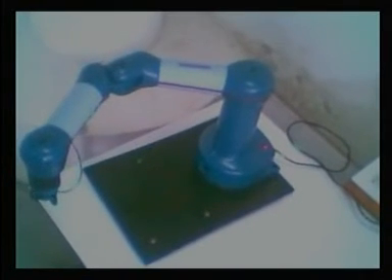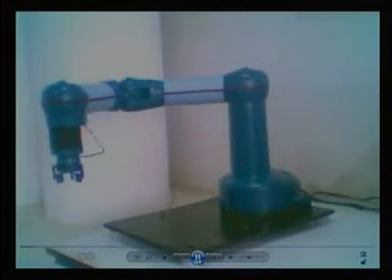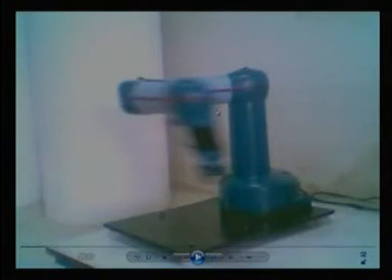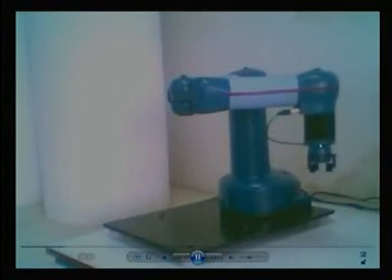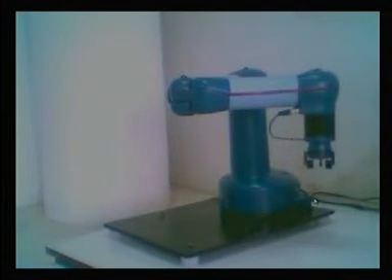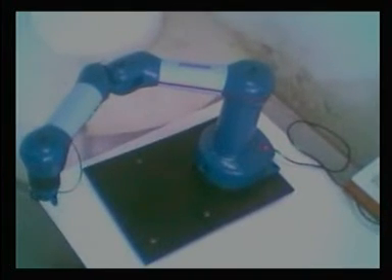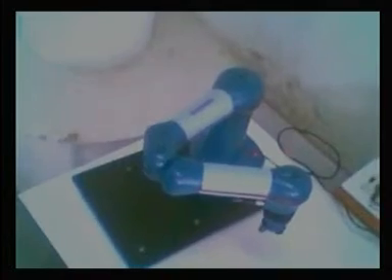Jaw motions are not counted in the degrees of freedom of the robot, as I told you earlier. So, this robot has 4 degrees of freedom. Which are the 4 degrees of freedom? This is the vertical one here, 1; there is an elbow here, that is the second one; at the wrist you have the third, so 3 revolute joints; and the fourth one is the prismatic one, which is moving up and down. This rotation was due to the rotation at the wrist, the third revolute joint, and this motion was due to both the first and second revolute joint rotation. Okay, so now we go back to our presentation.